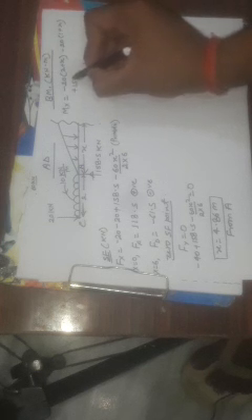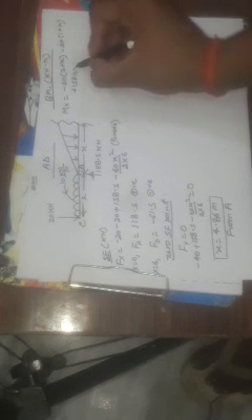The moment of this reaction force will be plus 158.5 into x. And we have already studied that the bending moment value for a section of a UVL is Wx cube upon 6L. It is in the downward direction, so it will be negative, and W is given as 60, so minus 60x cube upon 6, the length of UVL is 6. The power of x is 3, so the variation will be of cubic nature. I mention it by C, right?